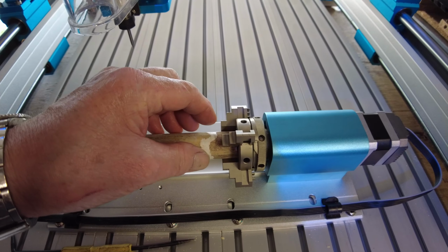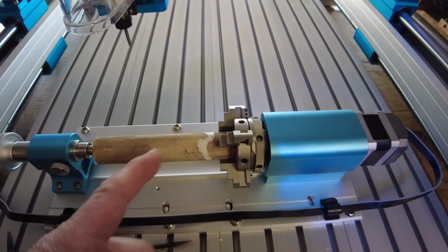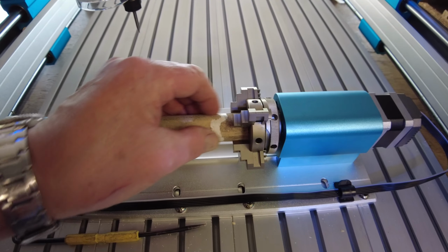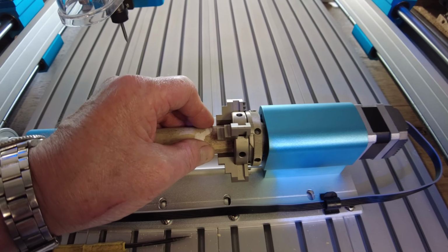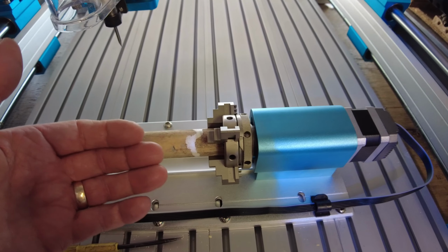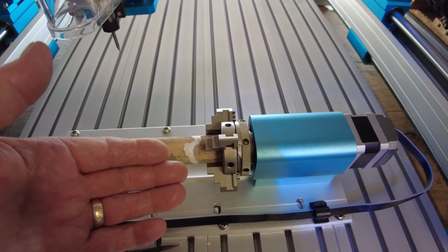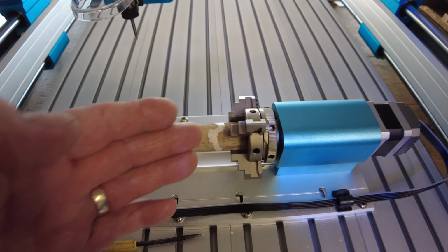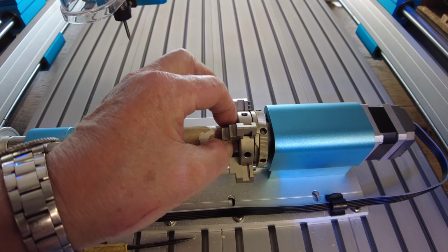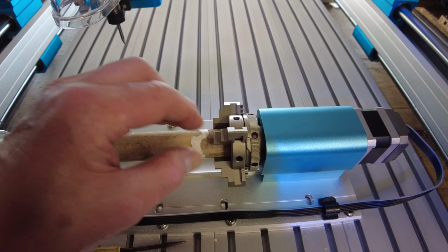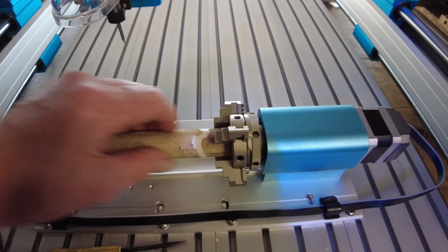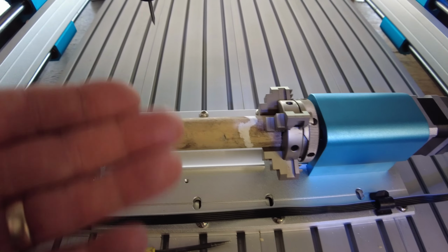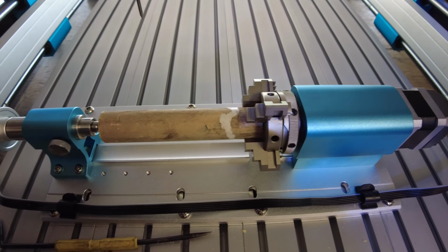So you could do that and then take some little bits off if you're doing repetition work to adhere onto the bottom. And I always, if I'm putting a false bottom on to grip it with, glue on both surfaces with a piece of white A4 paper between them, glue it together. Then when you take it off the bottom, the part that you've had in the chuck just separates off and doesn't damage the grain of the wood at the bottom. That's what I do anyway. Everybody has their own ways to do it, but that's what I do.